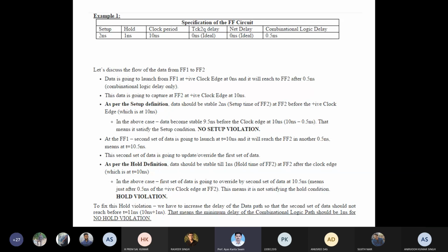So if it is FPGA, you know how FPGA differs from ASIC. When it is FPGA, your main requirement is that you have to do the design and meet your design requirement, meaning you are checking on the FPGA whether your specification is met, without going for an ASIC fabrication, which requires at least 3 months of duration along with the money, the investment.